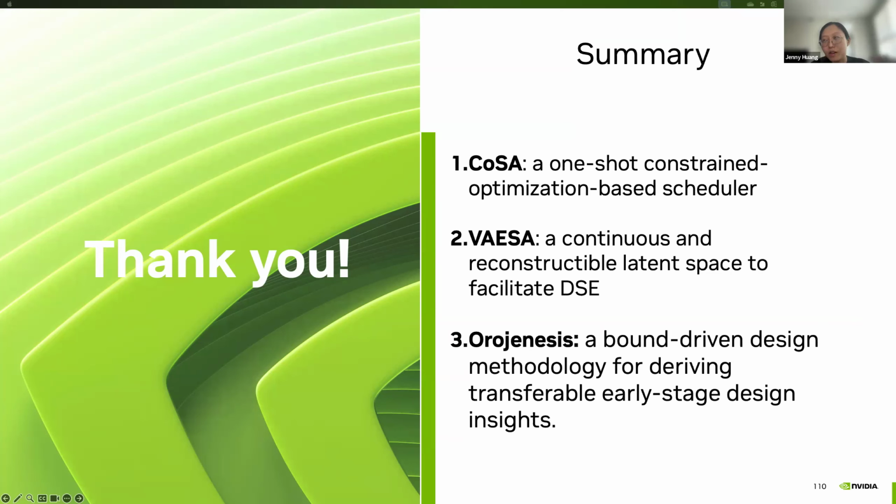In that case, if we're running input and output tiles in the same kind of loop ordering, because we have P and Q in the innermost loop, regardless of what you have in the outer loop, even if, let's say for the input, you have a K dimension, which is the output channel dimension that's irrelevant to your input tensor, because you're loading the P and Q in the innermost loop, you will always need to reload your input and the output, even though you have an irrelevant rank, which is the K in the outer loop.